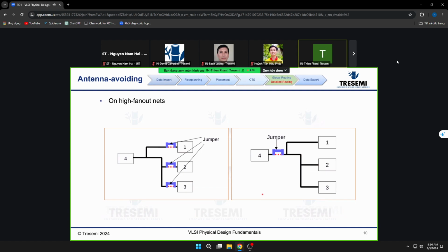So if you look at this one, say number one here, there are two ways of doing it, right? Let's say I have a violation on these 1, 2, and 3 because they're connected to the gate. So I can put in a jumper right here, 1, 2, 3, right? Or say, well, why do I have to do 1, 2, 3?